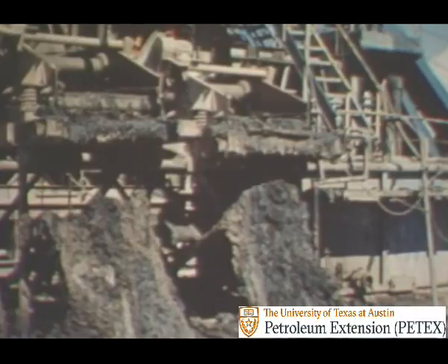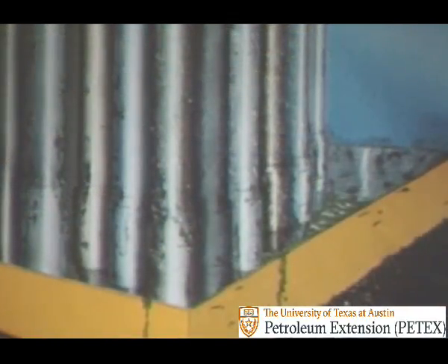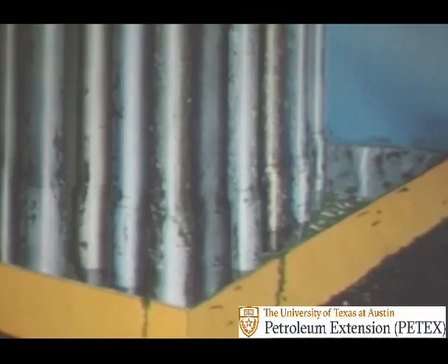Before drilling begins with the oil mud, fine mesh shaker screens have been installed to help remove the finer cuttings from the mud. If the finer cuttings and solids are allowed to remain in the mud, they cause the mud to thicken and increase mud treating expenses. Also, the screens will be kept clean to avoid losing good mud over the end. Oil mud is expensive, so mud salvage is an important economic factor.